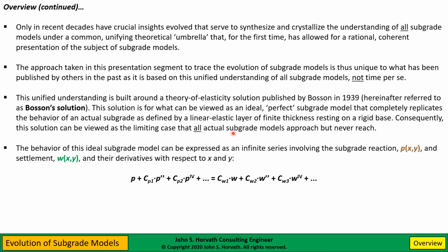So it was a rather interesting way to portray the solution. And I think this is really the unifying concept that I use. This is an exact solution. These two infinite series equated to each other. It's an infinite solution to a theory of elasticity problem that reasonably approximates a subgrade of finite thickness resting on a rigid base.